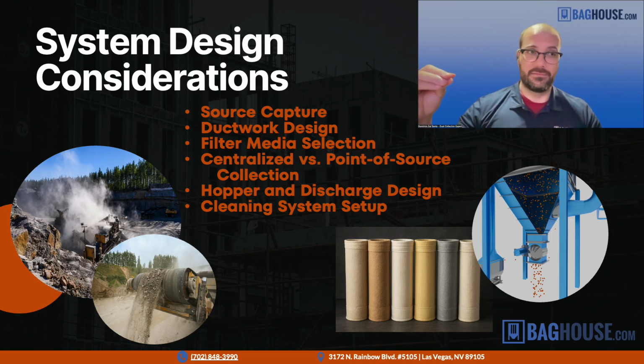Whereas if it's with hoods and ducting going right to the source, that same dust collector can handle dozens of pickup points throughout your plant. So we almost exclusively need to do dust collection at each source where it's generated. A few things with ductwork design.